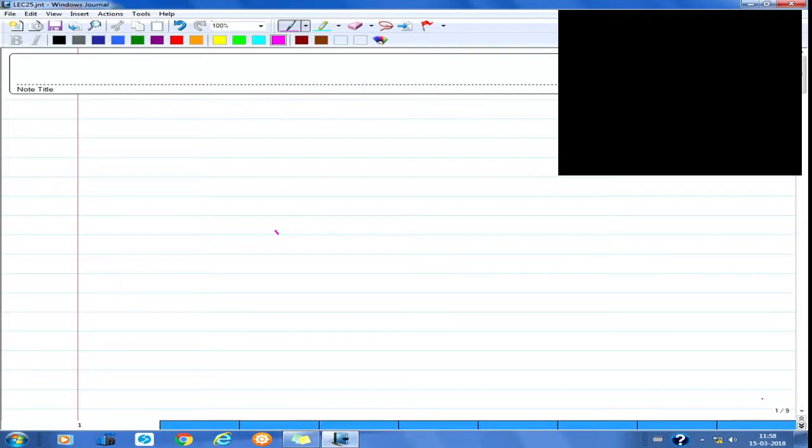Most of the time we actually use isoparametric, and say subparametric is in fact included in isoparametric when you use higher degree polynomials. Because what happens is when you interpolate the geometry, even if you use biquadratic polynomials in xi and eta and interpolate both x, y as well as the field variables, and if the element shapes are simple,